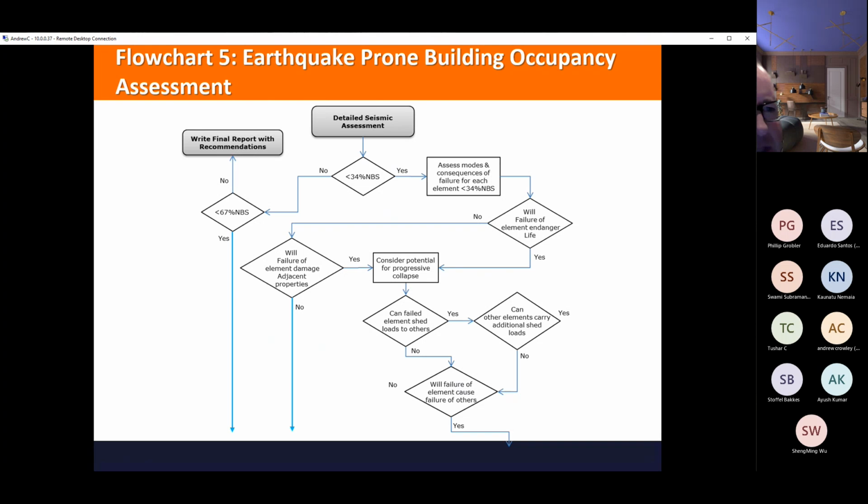This is something that comes up. This is another one I've invented. I've done a lot of structural assessments for seismic assessments, these ISAs and DSAs. And the question is, once your building is marked as potentially earthquake prone, are we allowed to occupy it? Well, the usual answer is yes, you usually can occupy it because of the condition in the event of an earthquake. But you really do need to consider in detail whether the building should be occupied or should be restricted as well.